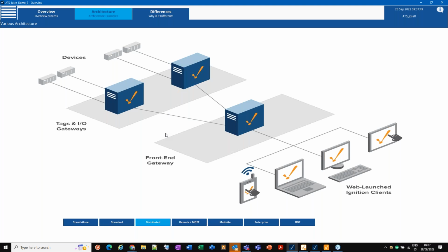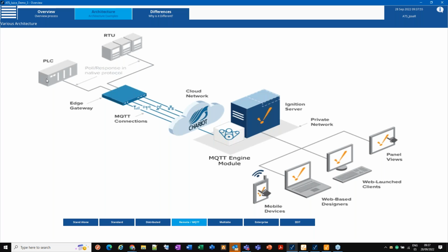Nowadays, we want to be more remote, especially for the energy system. So we can have a PLC that is quite far away, and it has a module that through MQTT sends remote information, which travels through the cloud and back into Ignition itself. So you can still monitor pretty much live data with a minimum disruption of your information. This edge gateway allows, in case there is a network failure, so we are talking about 3G, 4G, 5G network, internet communication,